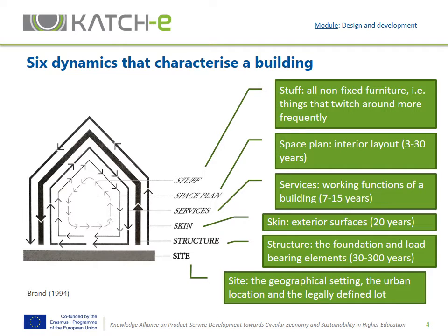The site is the geographical setting, the urban location, and the legally defined lot, and the lifespan is virtually unlimited. The structure is the foundation and the load-bearing elements, with a lifespan between 30 and 300 years. The skin is the exterior surfaces, typically with a lifespan of 20 years.